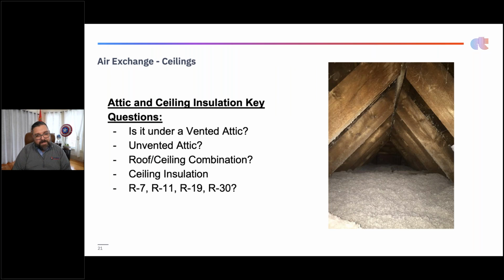Ceiling condition. So this is another spot because it's temperature difference and the ceiling is such a large surface area that it impacts the heat loss quite a bit. And really, you have to identify a few key aspects with ceilings. You need to know if the attic is vented, all right? And not just vented, that it meets the FHA standard when it comes to ventilation. So not just that there's a gable vent at the end.